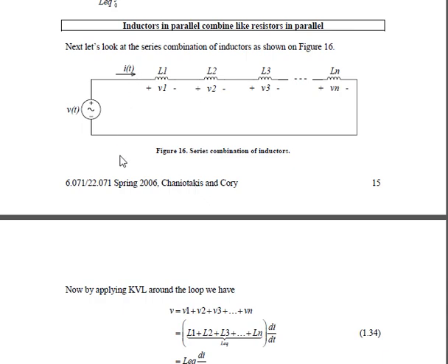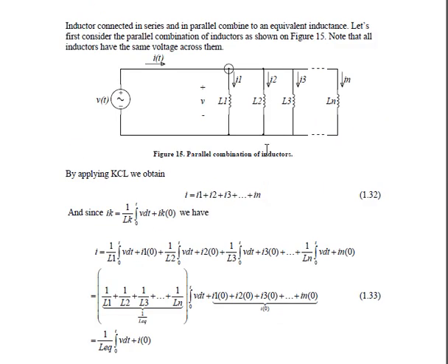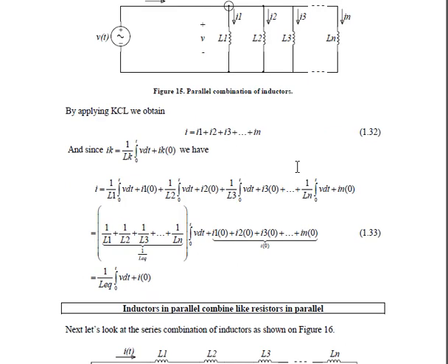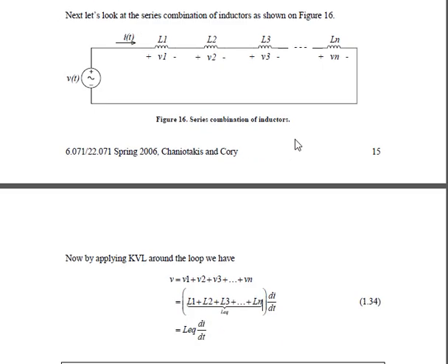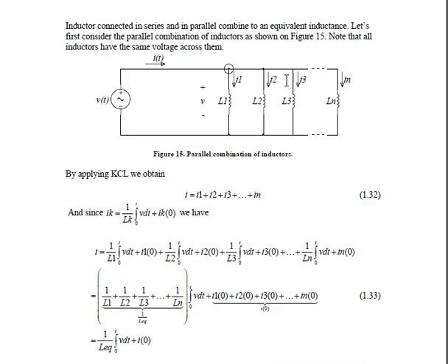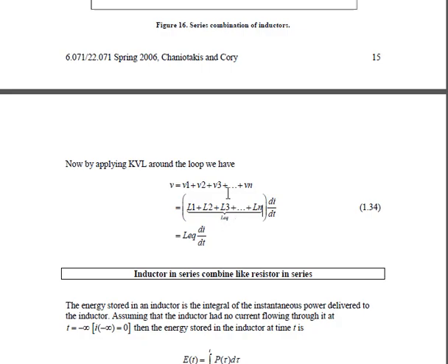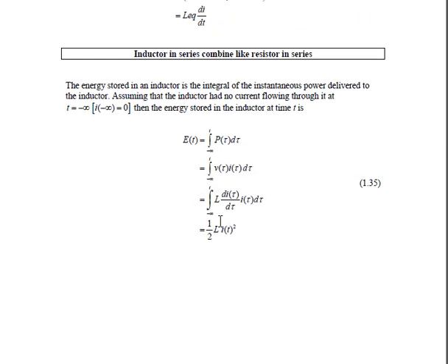This is quite different from our previous derivation on how to combine parallel and series connections of capacitors. For capacitors in parallel, we just add them individually, and for series capacitors we perform the reciprocal operation. But for inductors, in parallel we combine them using the reciprocal formula, and in series we just add them. So it is the opposite of what we discussed for the capacitor.